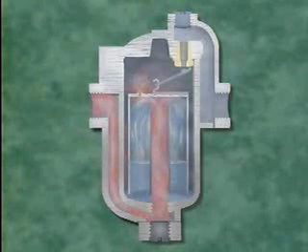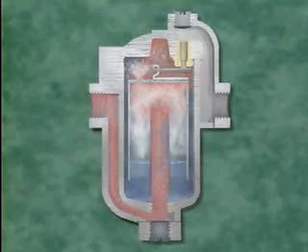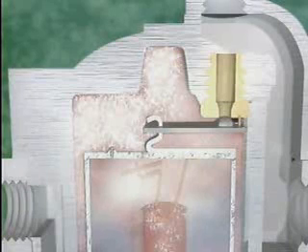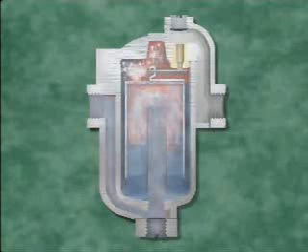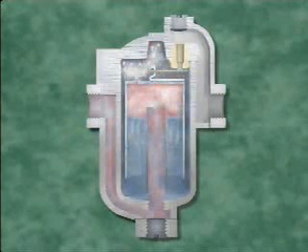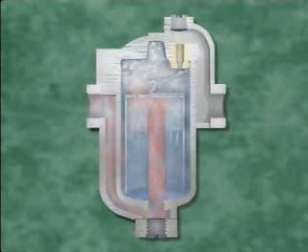When steam enters and accumulates to fill about 2/3 of the bucket, the bucket floats, and the trap valve closes, so no more condensate discharges. While the valve remains closed, air and non-condensable gases, which are less dense than the condensate, pass through the bucket's vent and collect in the cap area of the casing. Meanwhile, more condensate enters the bucket, and some of the steam in the bucket condenses. When only about 1/3 of the volume of the bucket is filled with steam, the bucket drops, and the trap valve opens.